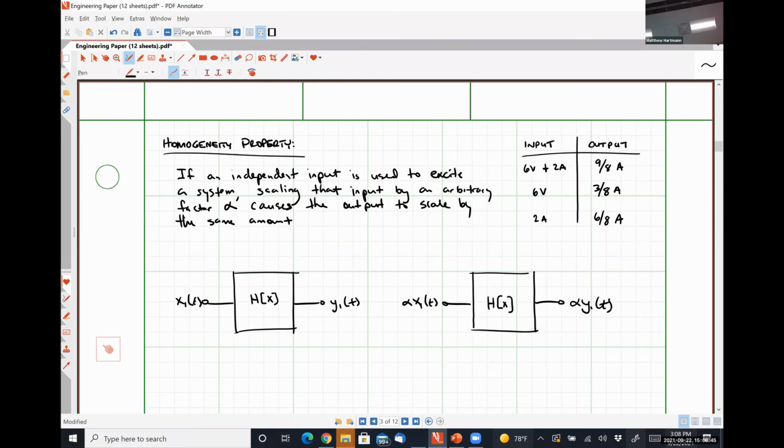It will absolutely work on circuits which contain dependent sources. But the turning on and off of sources that we did a moment ago only applies to independent sources. Dependent sources are always left on in the circuit. That's a fantastic question. Yes, sir.